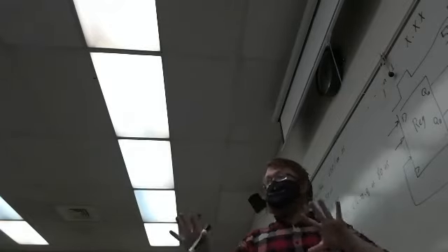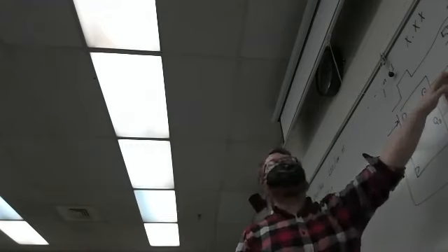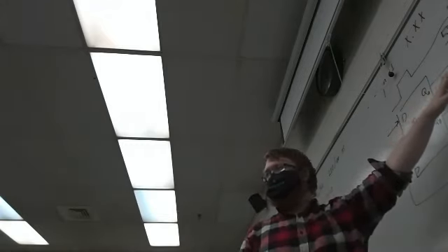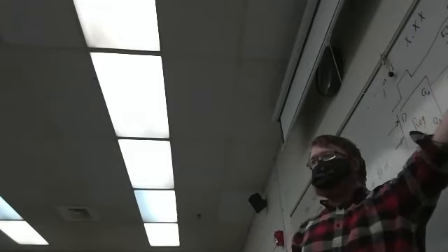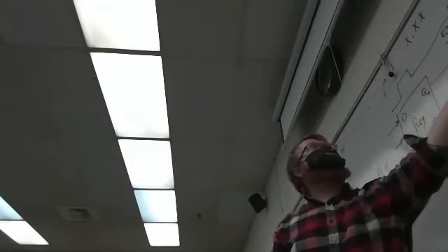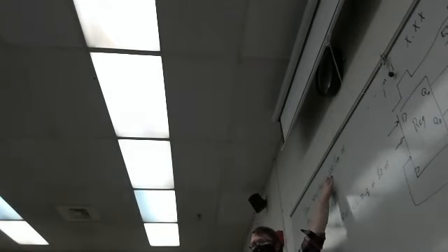Well, let's check, actually. Because what could happen, depending on what these numbers are, right? This clock happens, it takes a while to update this queue. And then the ALU has to execute whatever it's doing and then provide the number for that setup time. So I suspect the setup time is actually going to be 200 plus something. Okay, so you give the command to the register and you don't wait for that.